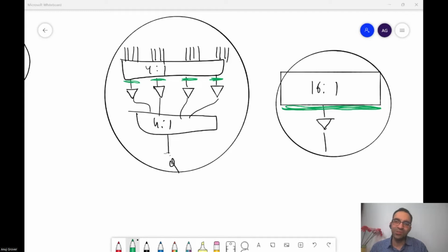Sir, yes, Anushka. For the sense amplifier, whatever input we give, we don't have to design a system to give that input, right? Like in the TVD course, I was working on the sense amplifier only. In that case, we gave SAEN as a regular clock signal, and then we kept bitline bar constant and incremented the bitline in steps. Will that be enough for testing or simulating the circuit, or do we need to do something else?